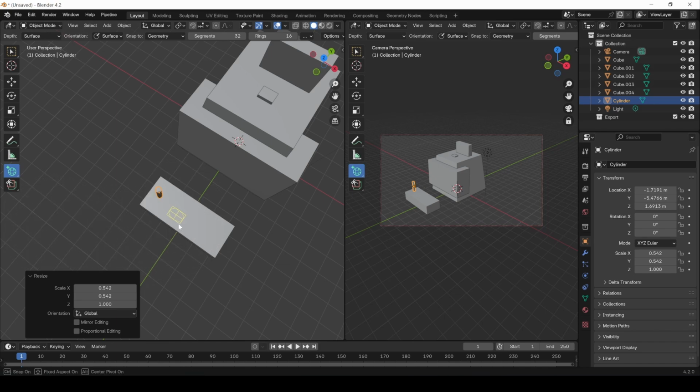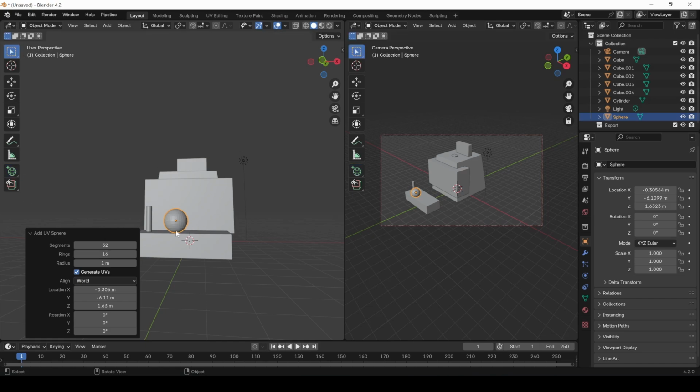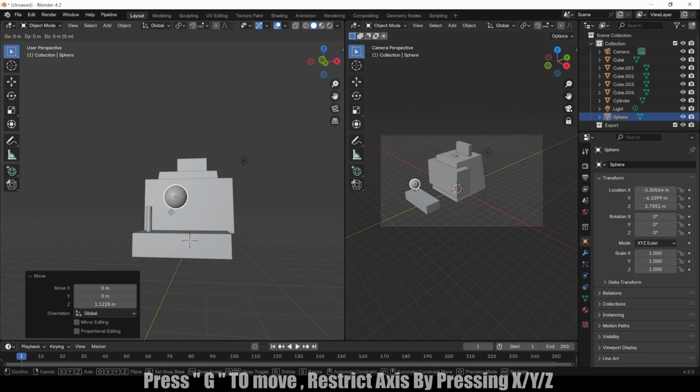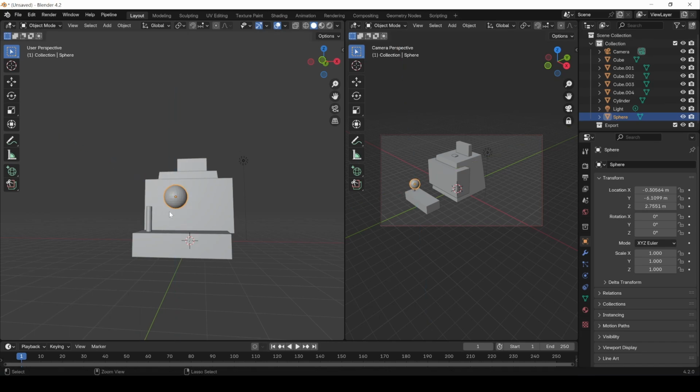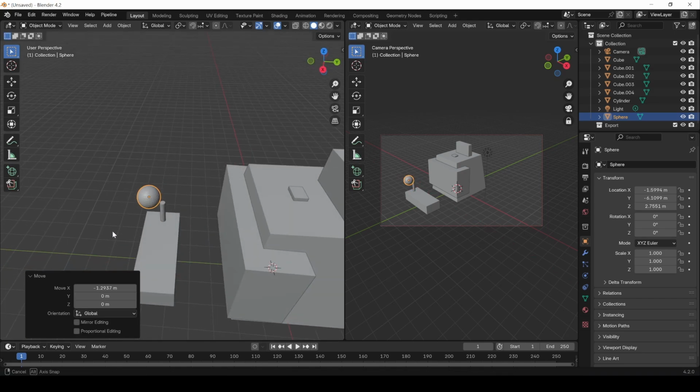Let's just go here and go to sphere and just create a sphere. Hold shift, then release and keep holding shift and press again. Now you have this. Let's make it 32 with 16, and now we have this. So J and move it on Z, then J and move it on Y, oh I mean X, J and move it on X, and just something like that.